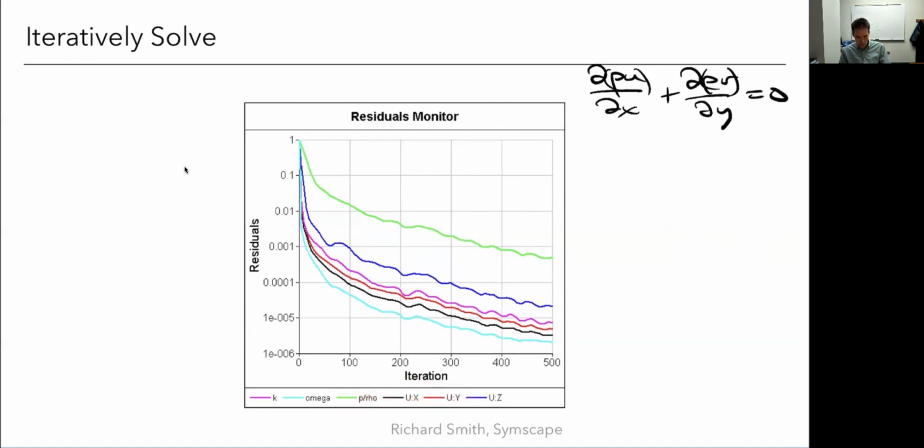So this must be an incompressible Navier-Stokes. I know that because these are turbulence model ones. So if we add a turbulence model, that adds 2 more equations, or it depends on the turbulence model. This is a 2-equation turbulence model. We'll talk about this much later. There's a k-omega turbulence model, so it adds some additional equations that I need to converge. If I had a compressible flow, then I'd have another one here. It could be pressure, temperature. These are related, so it just depends which one they show. But I basically want all these residuals to flatten out. But I would also look at not just these residuals, but I would plot the things that I care about. So say I cared about lift, I would plot that and make sure that that is also leveling out.